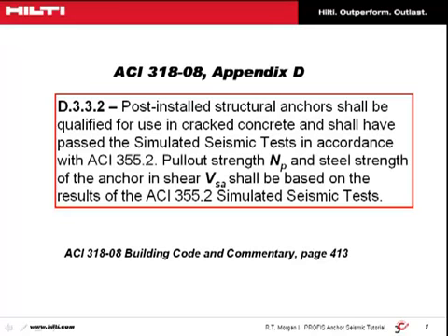PROFIS Anchor will only perform seismic calculations for post-installed anchors that have been qualified in cracked concrete for seismic conditions per the provisions of ACI 355.2. These anchors can subsequently be used for seismic design in either cracked or uncracked concrete conditions.